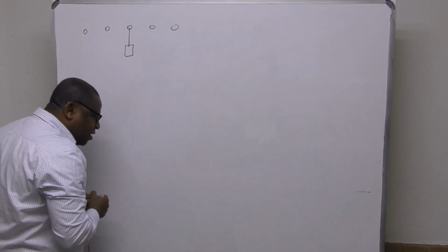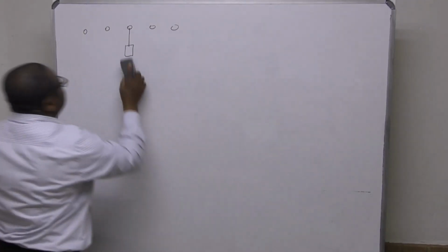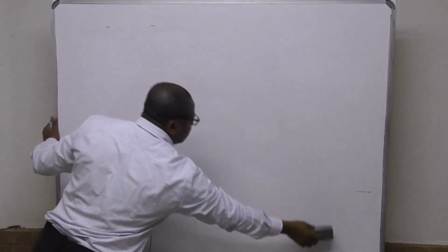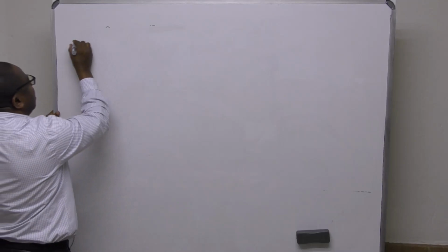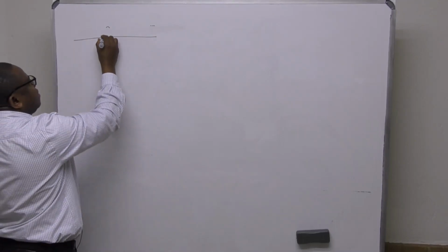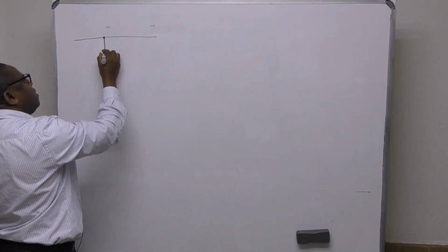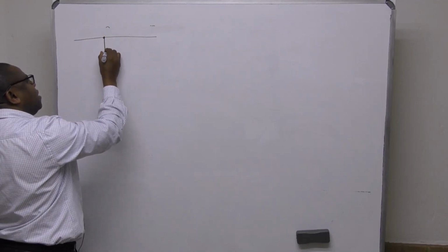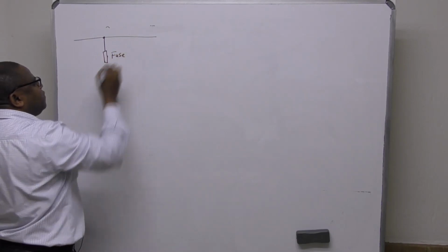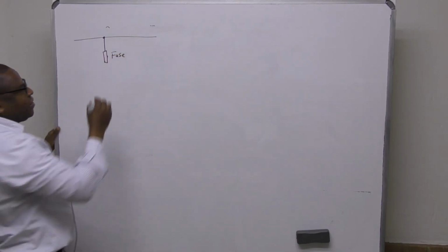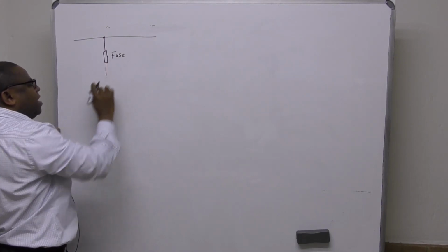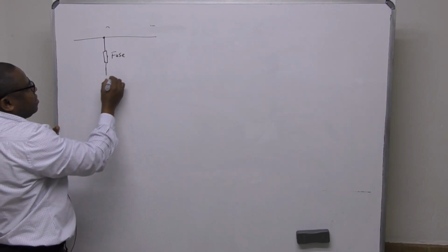But now, the way we start it, if you want to sketch, let's just put up a single line diagram like this. So I'm going to have a line first, all right? Then for the line, let's say there's a fuse, you can just sketch like that and say this is a fuse, all right? And then from the fuse, you are going to have an isolator, okay?